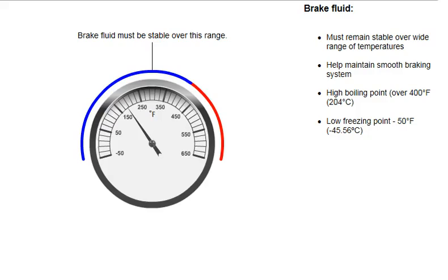Brake fluid must remain stable over a wide temperature range in order to maintain a properly operating braking system. Typically, these fluids have a high boiling point, over 400 degrees Fahrenheit, that's 204 degrees centigrade, and a low freezing point down to minus 50 degrees Fahrenheit, or minus 45.56 degrees centigrade.